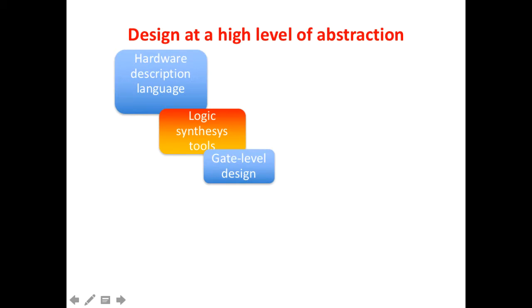Of course, you see that there are behavioral descriptions or more analytical descriptions of the behavior of the circuit. But in the end, after the use of this logic synthesis tool, you arrive at a gate level design. A gate level design is a design of a logical circuit at the level of single gates. And when you are at the level of single gates, then you can start to use a standard cell approach in order to design the complete chip.